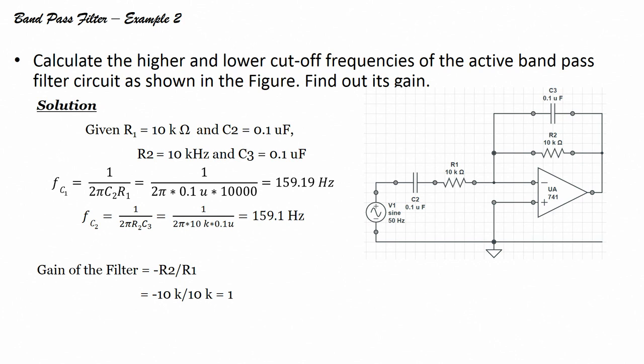if you are given a circuit, again this is a band pass filter, and you are applying the signal to the inverting terminal. So, it is an inverting amplifier, we understood. The gain of an inverting amplifier we already know: minus R2 by R1.